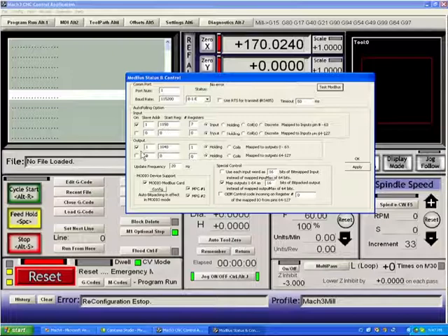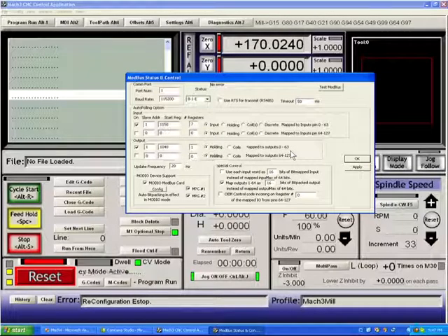Here's where we set an output. We have to tell the ModBus control whether we're outputting data from Mach3 to the holding registers or to coil registers. Some PLCs will use coil registers, some will use holding registers, and some won't care what you select here. The outputs are mapped to 0 to 63. This is to say that on Mach3, if you set an enable pin, for example, to port 0, pin 26, the data being transferred here is going to reflect those pins in the program.